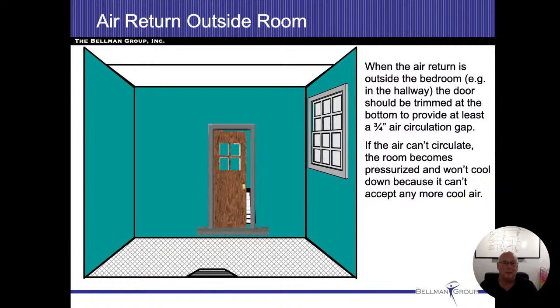If they do that, then that obviously defeats the purpose. So a little trick that I do when the furnace or the air conditioner is running and I have a central system in there: I'm going to close the door, and I'm going to close it slowly. If the opening is small enough, then that airflow is going to pull that door shut. And as it pulls the door shut, I know I have to either put a vent in or increase the gap under the door. All right.